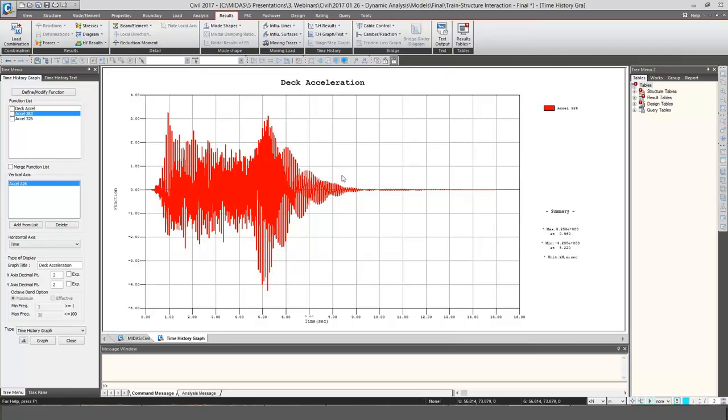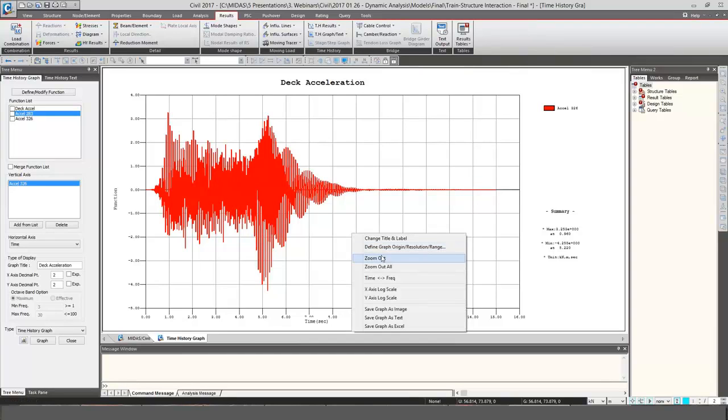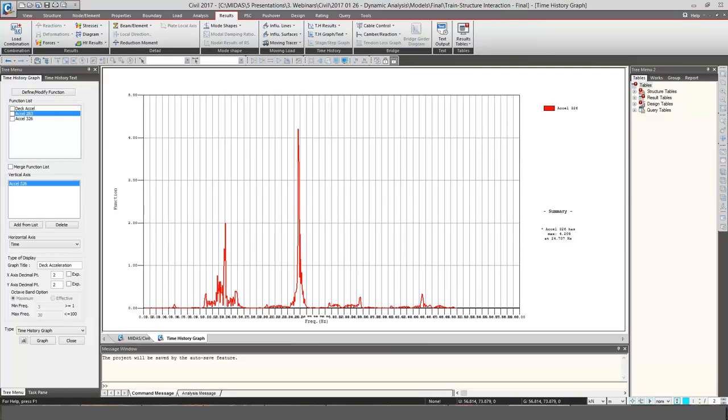And when we do these checks, we need to make sure that we've set up enough time for the time history load case so that the accelerations reach zero level. And once we have the histogram, we can, as I said, apply a fast Fourier transformation and see where most energy goes, in what frequencies from the excitation coming from the train load, in which frequencies it mostly goes.